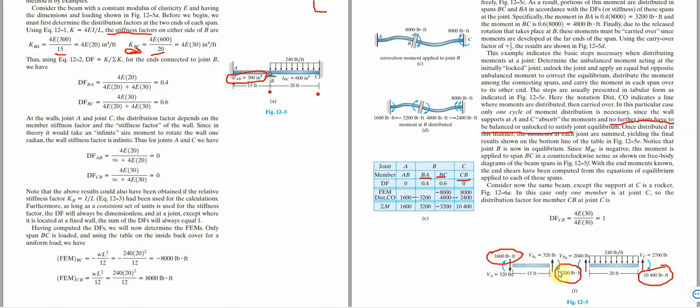And if you look at the sign convention, I explained the other time that when we make a cut on a beam or a member, the sign changes. That is, if it's going upward at this side, it is going to be coming downward, or the rotation will change at this other end. This one is coming clockwise here, but here it is coming anti-clockwise. That's what I'm trying to explain here. So let me proceed.